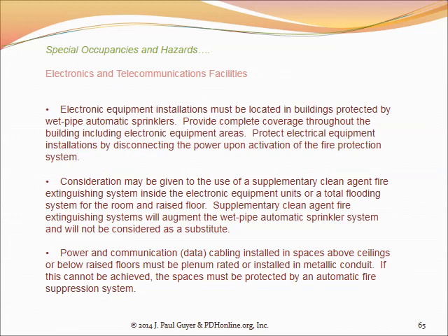The data processing facilities and facilities with electronic equipment are usually located inside buildings that are protected by a wet pipe automatic sprinkler system. However, generally speaking, you would want to use a clean agent fire extinguishing system in the actual space where the electronic equipment is located. And the power and communication or data cabling installed in spaces above ceilings or below raised floors must be plenum rated or installed in metal conduit.